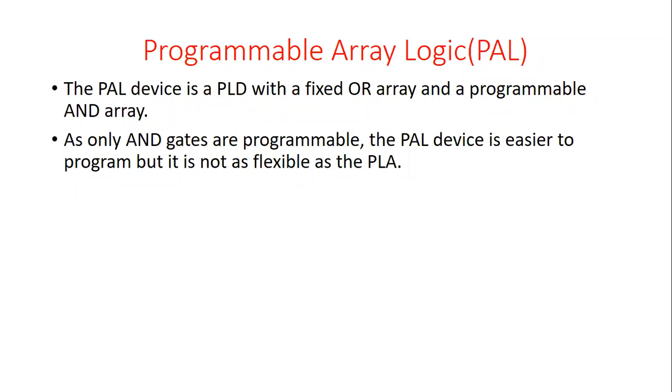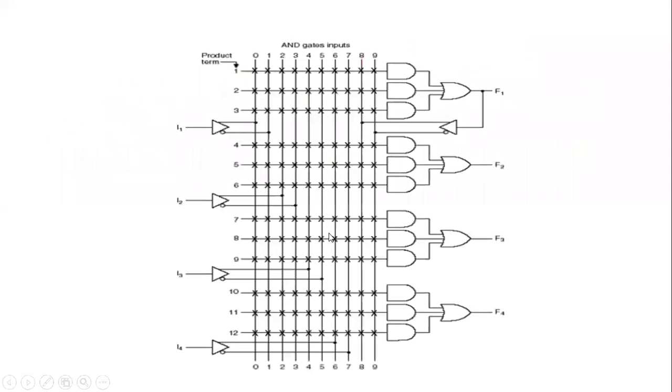That's why we are going to implement this by using the K-maps. So after implementing this by using the K-maps, we need to consider the circuit diagram for this like this. See here what we are having: 0, 1 lines represent the I1 input, I1 bar input. Next, 2 and 3 represent the I2 input, I2 bar input.